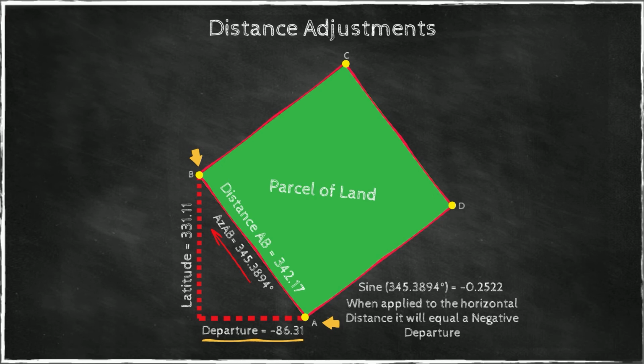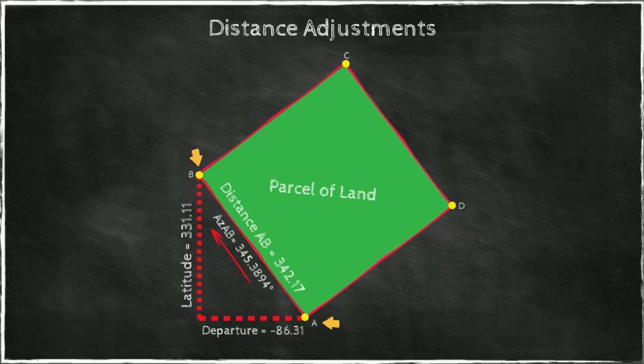And that is very valuable. It does the sign tracking for you automatically. That's one big advantage of using azimuths in all your calculations. It has a tremendous safety factor in it. In the case of the y-coordinate for point B, it's simply the y-coordinate of point A plus my latitude. In this case, the latitude ends up being positive, so y increases from A to B.